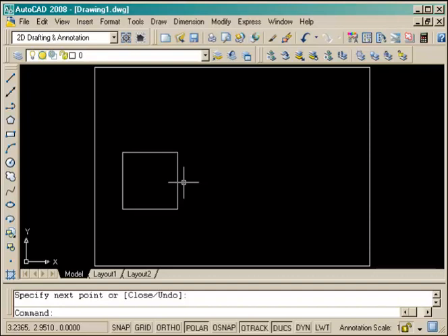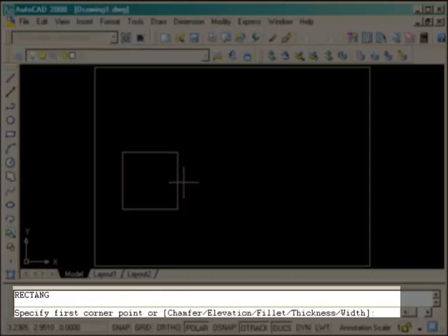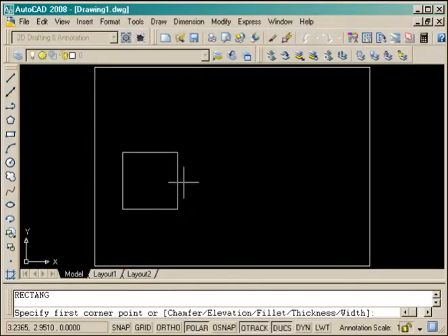The second one, just to the right of it, we're going to use the rectangle command for. What that needs is 2 points, a start point for one corner and then the points for the opposite corner. So this time we'll start the rectangle command just by typing in REC, and the starting point in the bottom left corner is 4.5, 2.